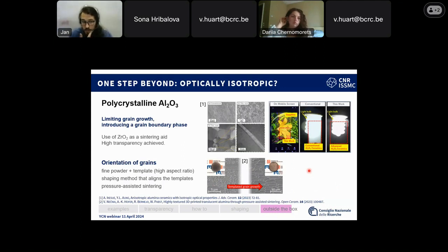And the shape of particles should be close to regular spherical to achieve high density of packing, and as a result, fewer defects, more uniform microstructure of green bodies, and high transmittance.